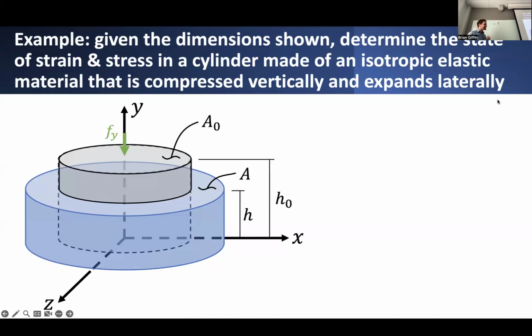In the present context, if we're trying to compute longitudinal strains, assuming small deformations, in other words, assuming that the displacement of the cylinder is relatively small, I'm just exaggerating the displacements here, we can make some approximations. In particular, if we're only given measurements of cross-sectional area and not necessarily the diameter, we could transpose these into equivalent measurements of the change in the diameter of the cylinder.